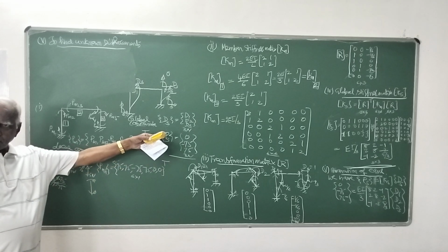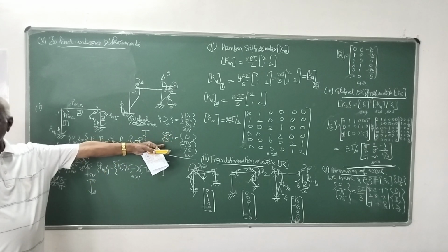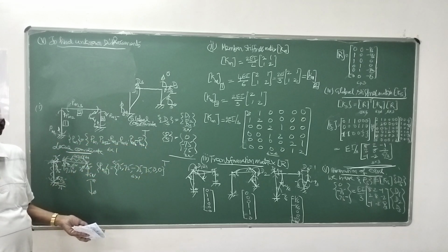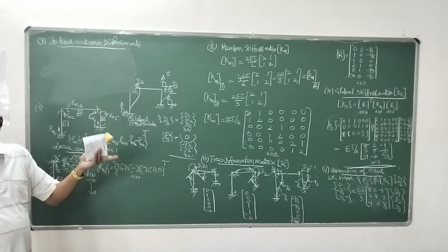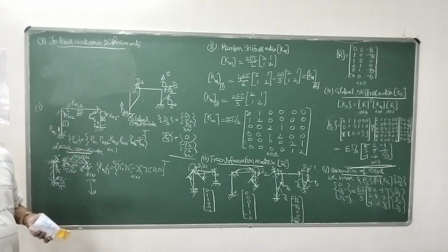Analysis means you have to determine internal member forces as well as displacements at various joints. That is how we define the analysis, along with, of course, support reactions. Reactions you will get automatically from the static conditions, nothing other than that.